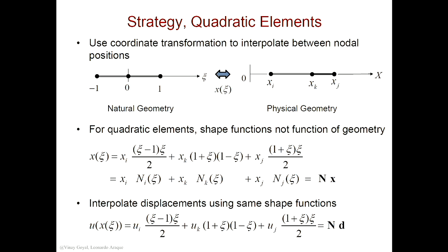This is incredible. Don't you agree? After I put this mapping in with these shape functions, it goes from this to minus 1 to 1 with a center node at 0. Every single element, I can do that. Isn't that interesting? I can take every element, which may have a different size, and this node could be more to the right or more to the left. I put it through this mapping, and it gives me minus 1 to 1 and a node right in the center.